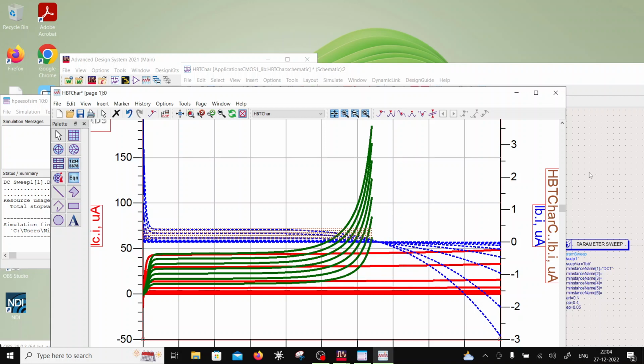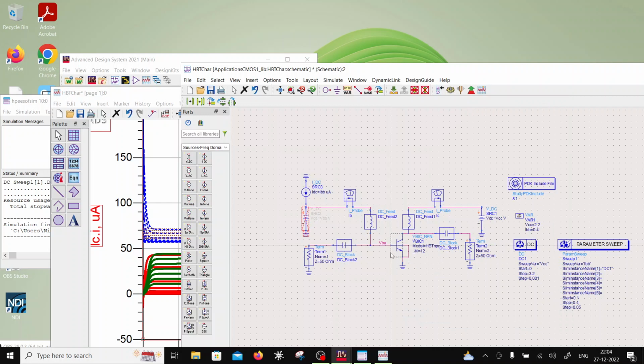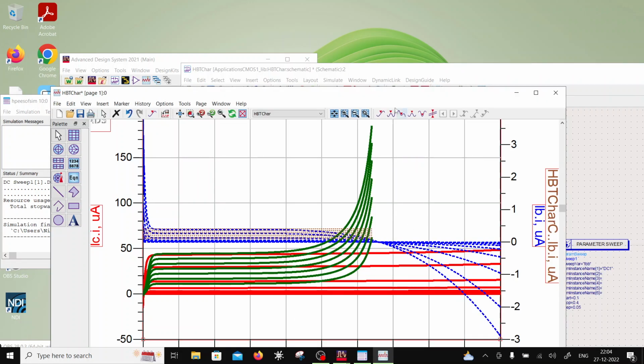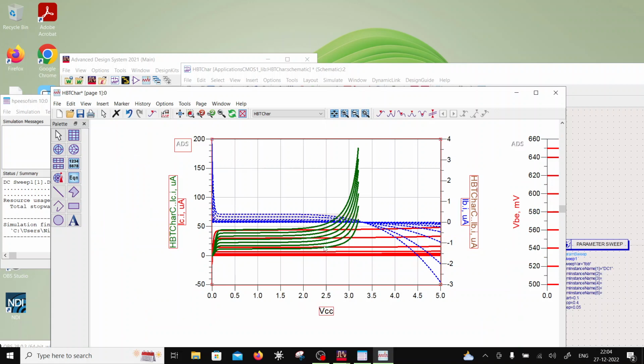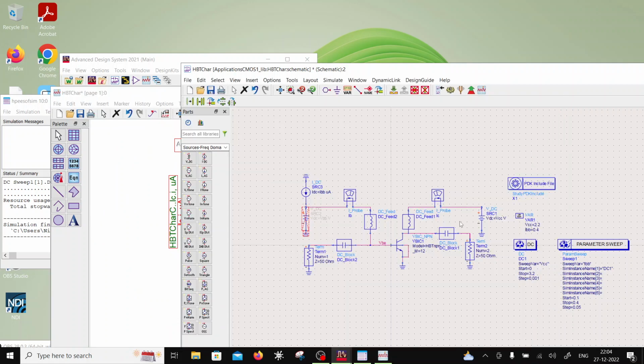Okay, and all the collector base leakage due to breakdown is going into the base emitter junction and gets amplified by beta and then shows up in the collector current. So the avalanche is enhanced because of this positive feedback. So biasing with the current source is doing that.